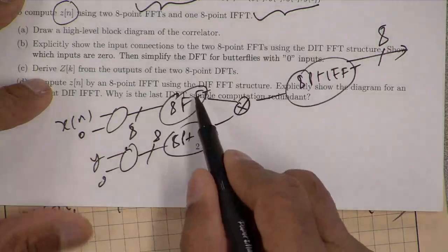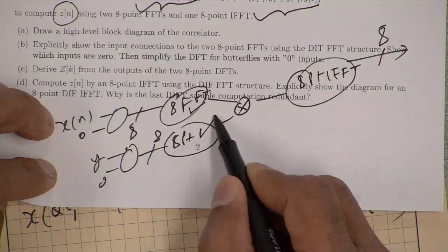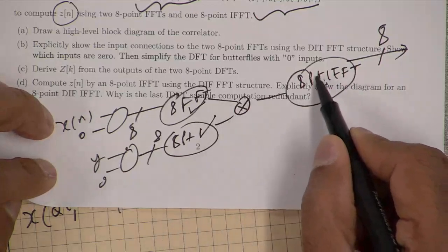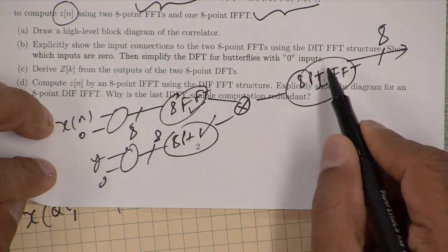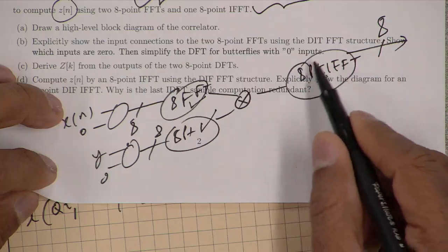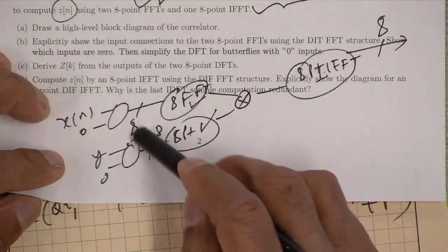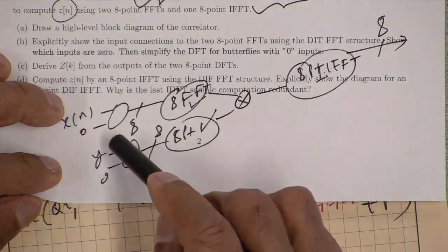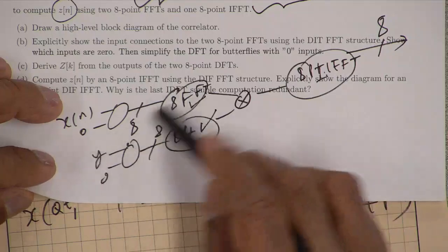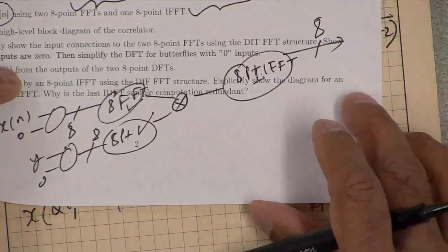So draw this 8-point using decimation in time, and the same here, decimation in time. For the IFFT, use decimation in frequency, conjugate the twiddle factors, and scale by 1 over n. But here I want to see, if you line them up, where 0, 1, 2, 3 are, where the zeros are, how they're appended, and where they're placed. If you don't do that right, it won't be computing the right things.